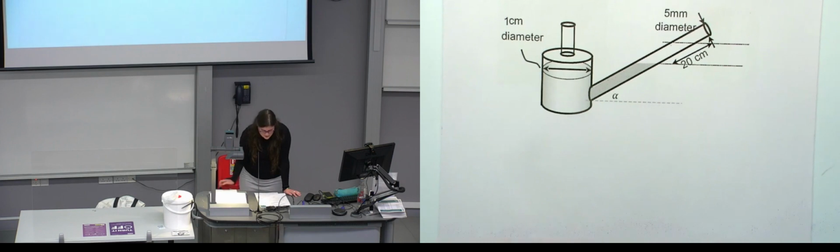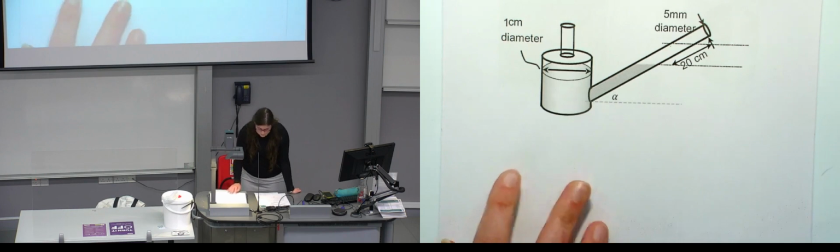So question 3 is this incline manometer, and it says it's filled with oil with a specific gravity of 0.85. The cistern is initially open to the atmosphere, and then a pressure line is connected that creates a gauge pressure of 500 pascals. Then the oil surface in the manometer tube is displaced by a distance of 200 millimeters, and it asks for the manometer angle alpha.